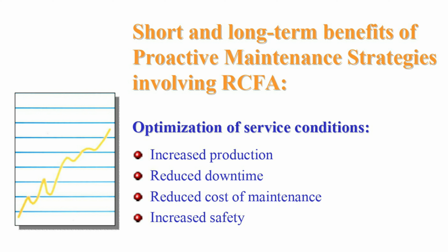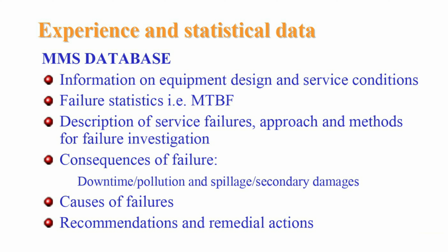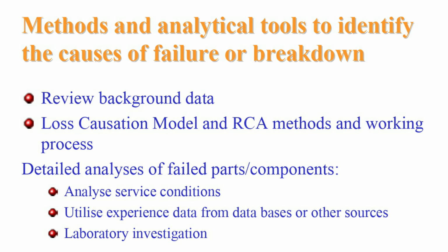Experience and statistical data, MMS database, information on equipment design and service conditions, failure statistics, for example MTBF, description of service failures, approach and methods for failure investigation, consequences of failure, downtime, pollution and spillage, secondary damages, causes of failures. Recommendations and remedial actions. Methods and analytical tools to identify the causes of failure or breakdown, review background data, loss causation model and RCA methods and working process.